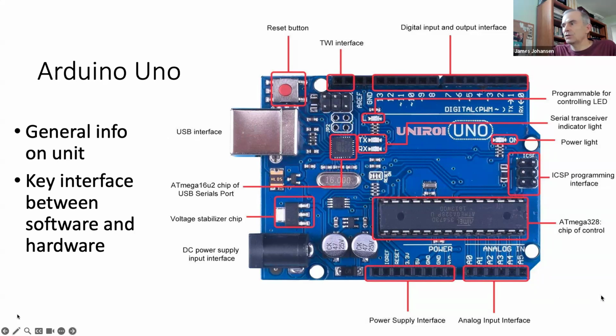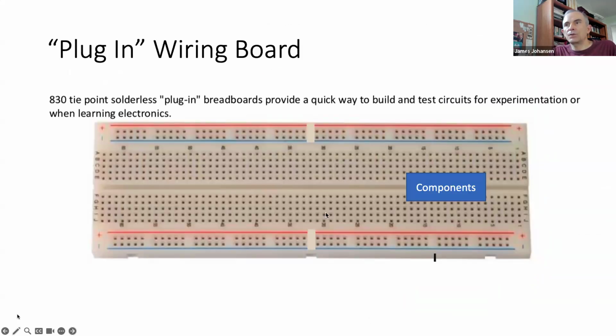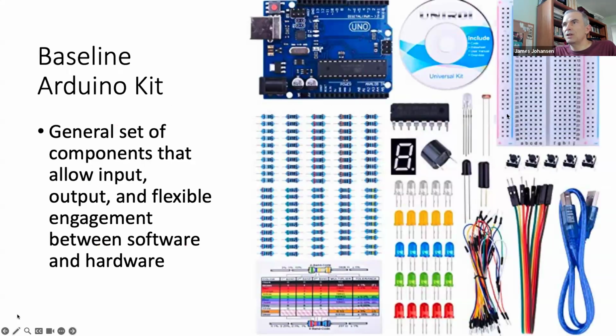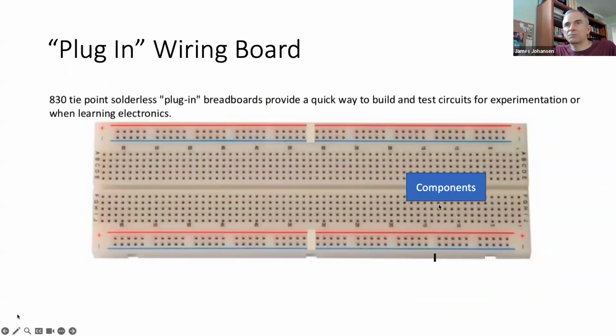And this other side, this is how you're communicating with your breadboard. This is a larger breadboard than what we saw in the earlier picture. You may get something this size, or something a little bit larger. These lines going like this mean that all of these along here are connected together. There's a wire in the back that connects them. So if you stick a wire in here and another wire over there, they have a physical connection. Here, these are all the same, all connected down this line.